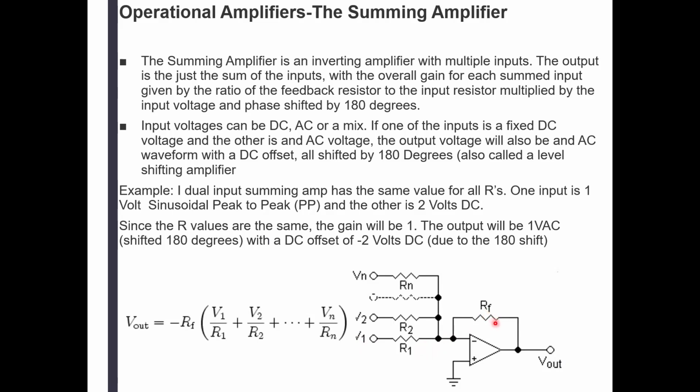All right. We have a resistor that is 10 kilo here, and all of those resistors are 10 kilo ohms. So 10 kilo, 10 kilo, 10 kilo, 10 kilo, 10 kilo. If we apply 1 volt, then the gain for that voltage applied to this point only is going to be 1 volt times the gain, which is 1, because 10 kilo divided by 10 kilo is 1. That's our gain. We're going to have 1 volt.